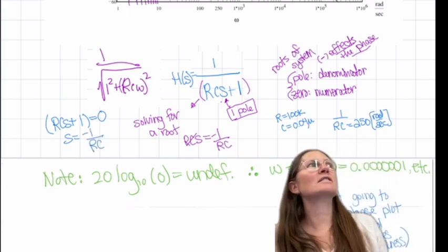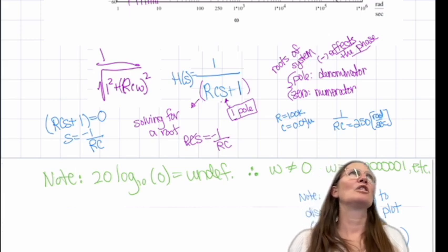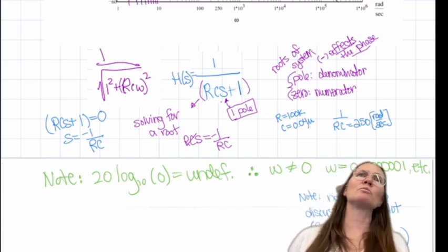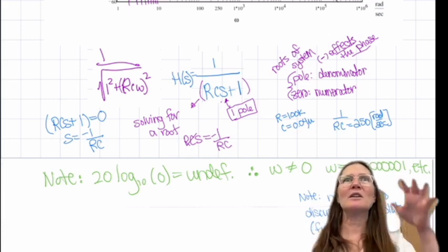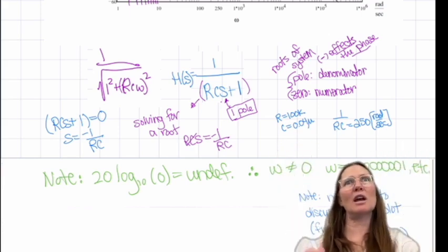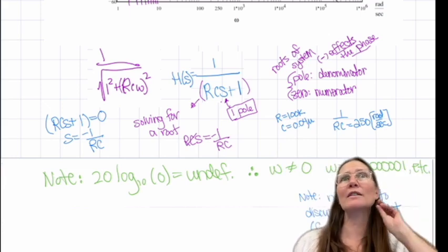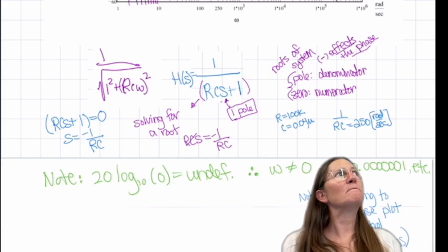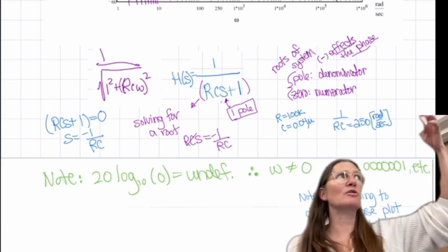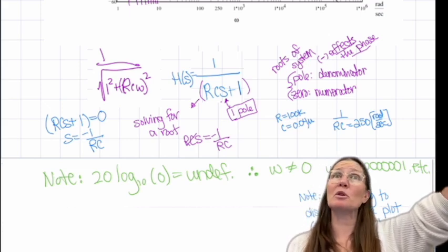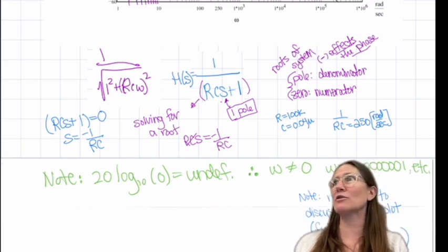So like if you have a polynomial, you usually have to take the quadratic solution for that one, but then it becomes a factored form, and then you set each of those factored forms equal to 0 to solve for the S's, for both the numerator and denominator, for poles and for zeros. Correct. So whatever functions you have, we want to get it into a simpler form like this before we can then graph it. So this is called the standard form.